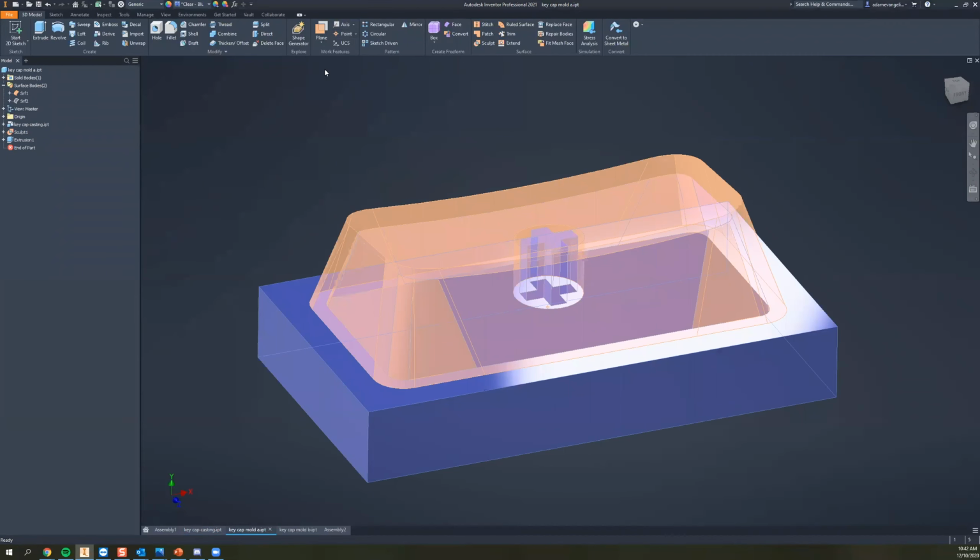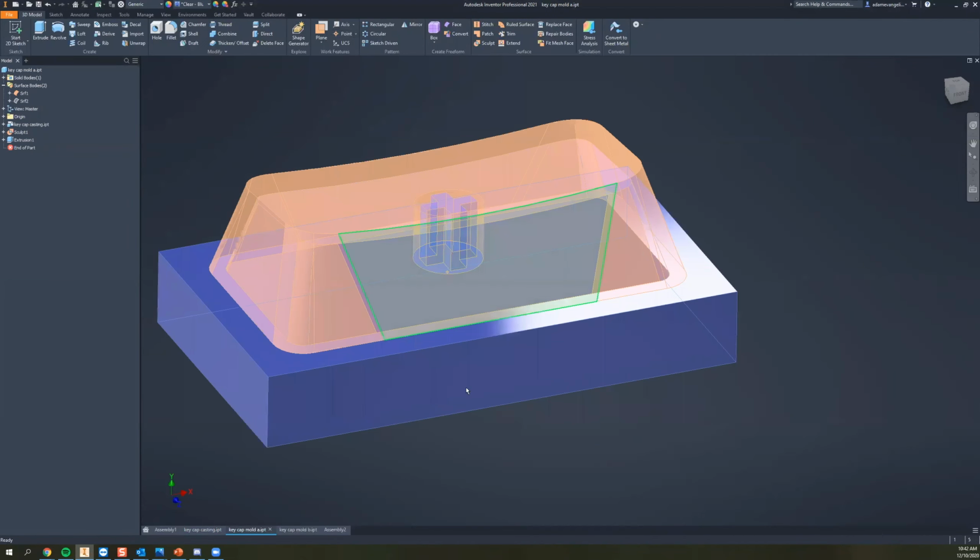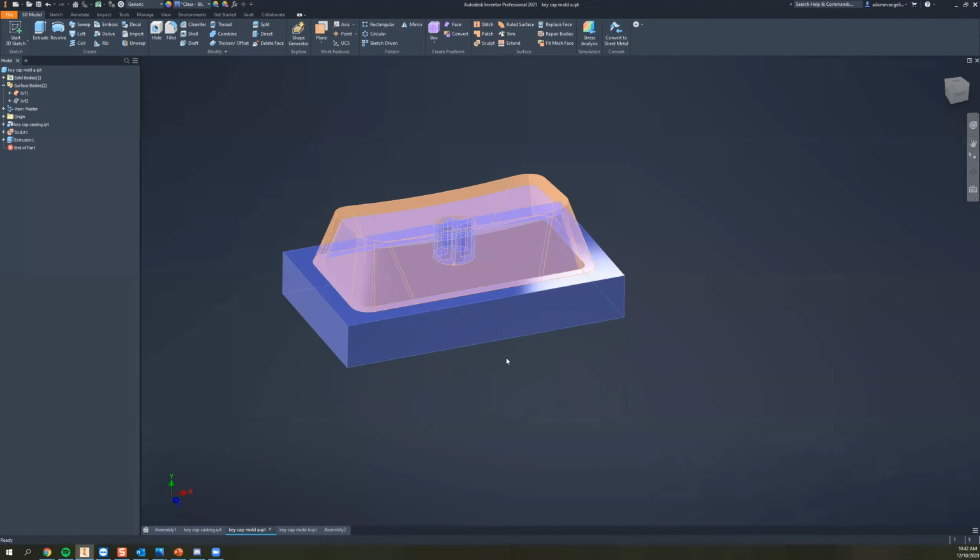I think if you take one thing away from everything, it's please define your models using parameters. That's why Inventor is called a parametric modeler. I mean, yeah, sure, it generates d0, d1, d2 and stuff, right? When you're working in Inventor, please name those. It makes your life so much easier in the future, especially when you do things like what Adam's doing, where you're linking parts together, right? You don't want to link d0 to something else. Exactly. Just makes it so much harder.